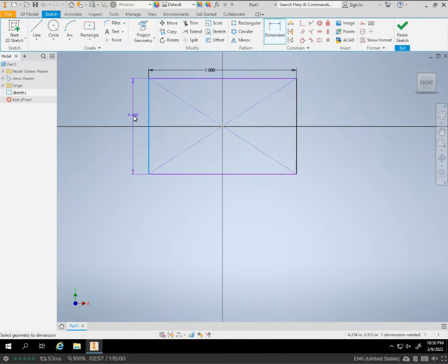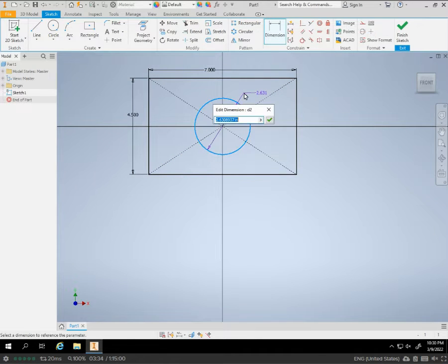And I think I already pretty much did it, 4.5 inches tall. So it's pretty close already. So it kind of kept the proportion that it needed to. All right, so to kind of shortcut the process and make this a little bit easier to do, we're going to go ahead and put a circle in the middle. And this circle is going to be 3 inches in diameter. So you can pop it there if you like and go ahead and put 3 on it, or you can type in 3 as you go along.